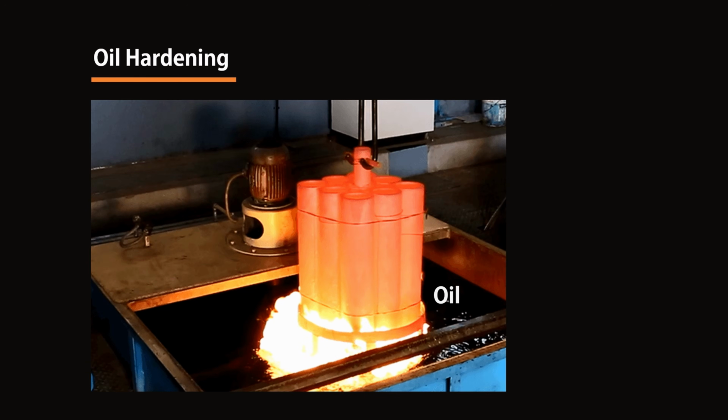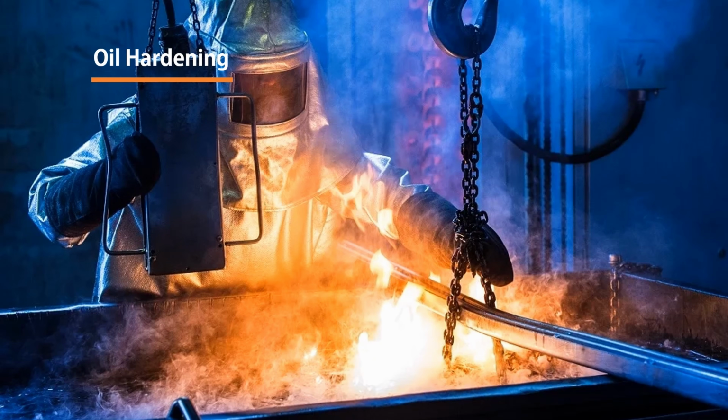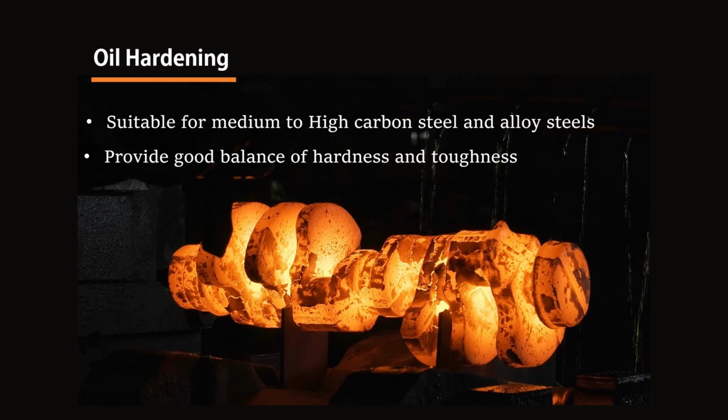Next is oil quenching or oil hardening. In oil quenching, the metal is cooled in oil, which provides a slower cooling rate than water. This reduces the risk of cracking and distortion compared to water quenching. However, oil quenching has its own challenges, such as fire hazard risk, which requires proper handling and disposal of the oil, and making it costly as compared to water hardening. Oil quenching is very useful for medium to high carbon alloy steel, and components that require a good balance of hardness and toughness, such as gears, bearings, and crankshafts.